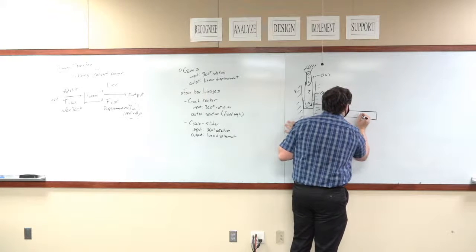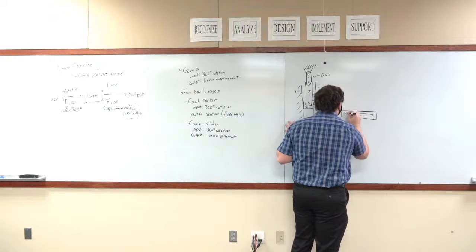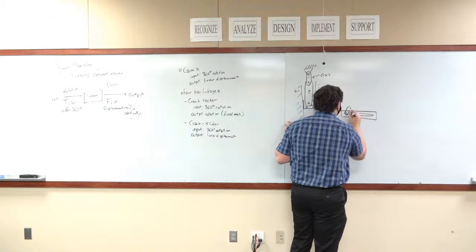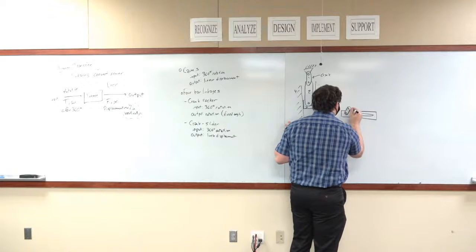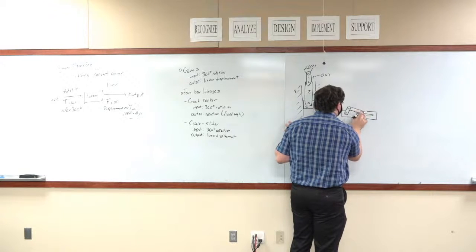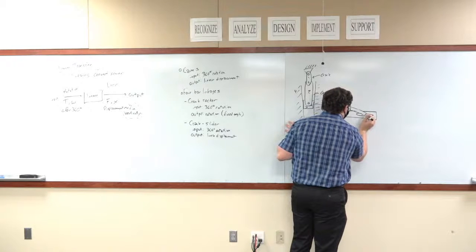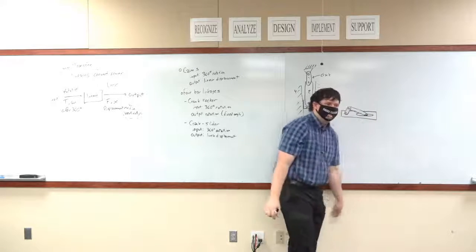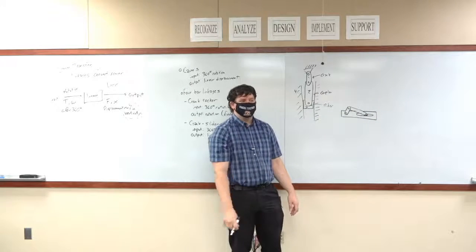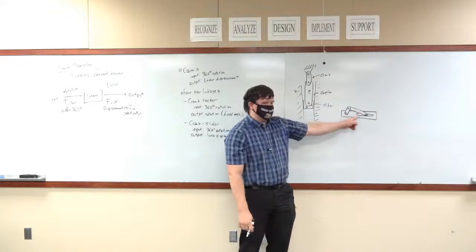As a representative, if you wanted to have an actual mechanism, you could have something where your ground linkage looks like this, has a slot in it, has a spot where the crank comes out, has a coupler, that goes into maybe a round slider, a wheel or something, and that goes inside of your slot.